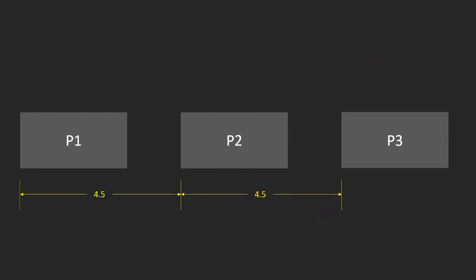And I'm going to call it P1, 2, and 3. And I'm actually going to use the P1 as my offset. So G154 P1, maybe you're familiar with. We're going to use P1 for the first part and 2 and 3. But I know that these parts are 4.5 inches apart. So we'll circle back to that, but this is kind of how I want to set it up.